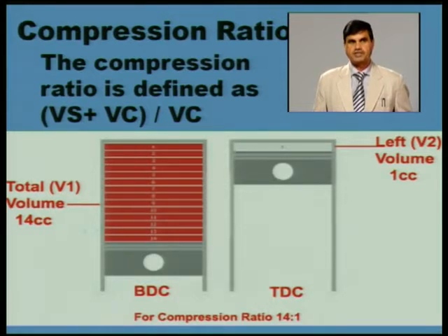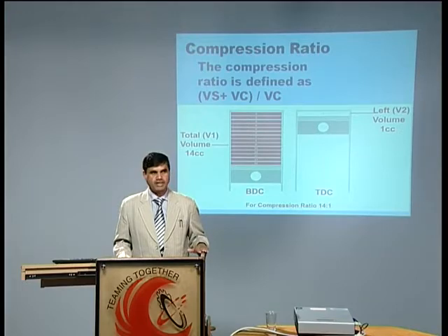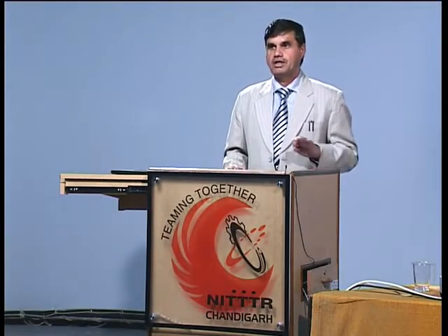This compression ratio is a very important parameter of an engine. When we are designing an engine, serious checks have to be kept on this compression ratio. In a petrol engine, if we have increased this compression ratio, it will create a lot of problems in combustion. In a diesel engine, if the compression ratio is kept low, again combustion will be very difficult.